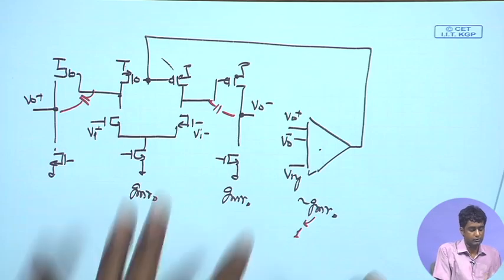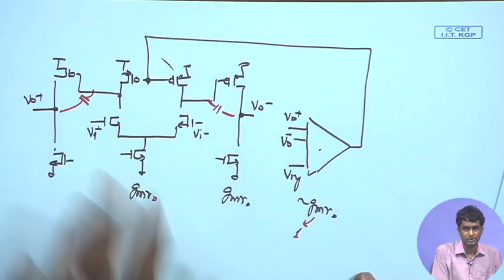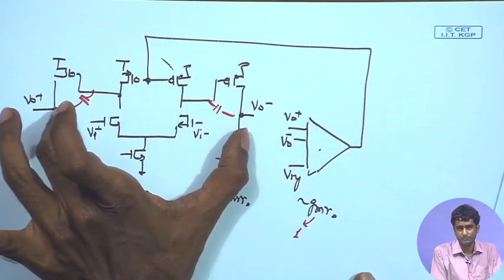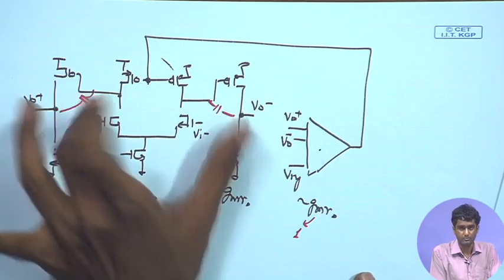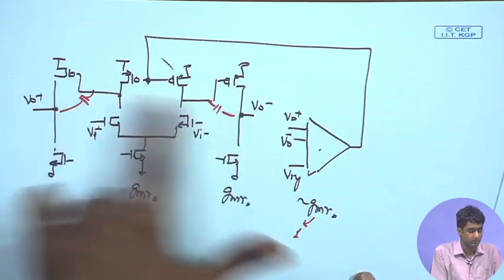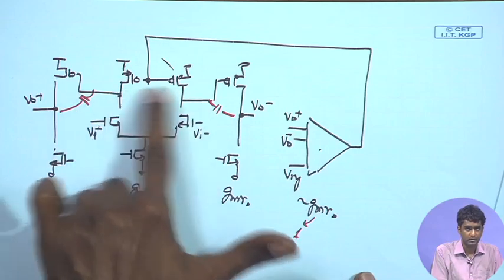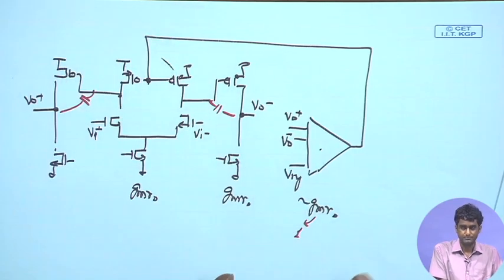There we need to compensate the individual loops also because they are not aligned with the overall differential loop. So, the individual common mode loops for the output stage and the differential amplifier are separate.